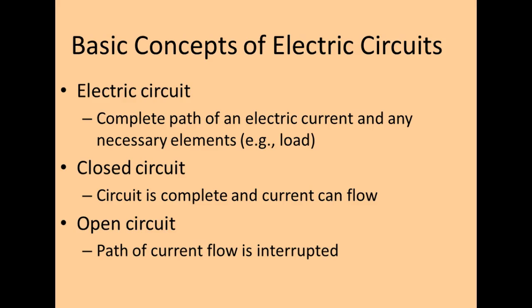I've got a 3-load series circuit. In a series circuit, we know that voltage is shared based on their resistance. But what happens to my amperage? Well, the amperage in a series circuit is all the same.